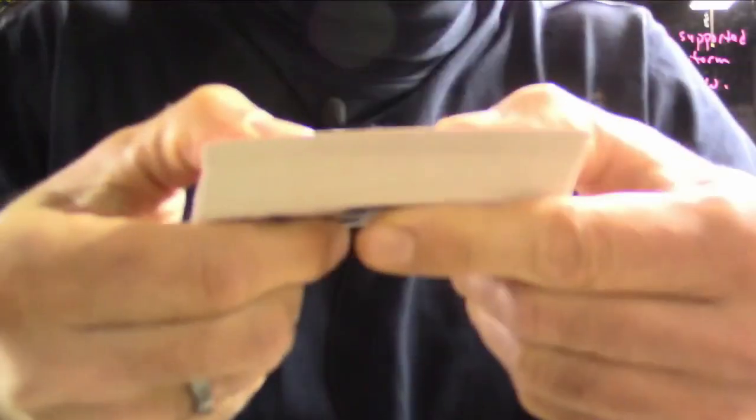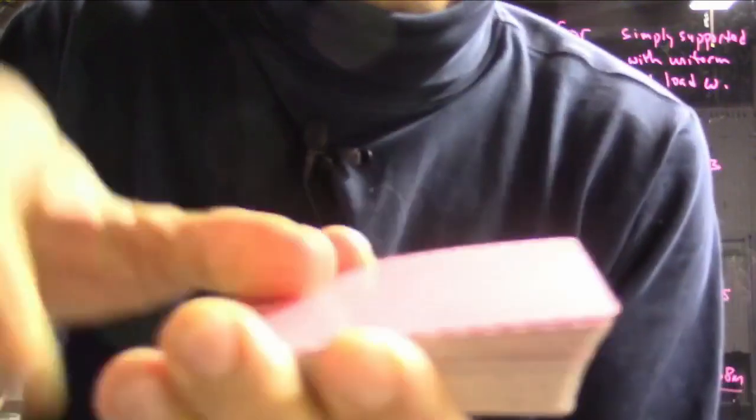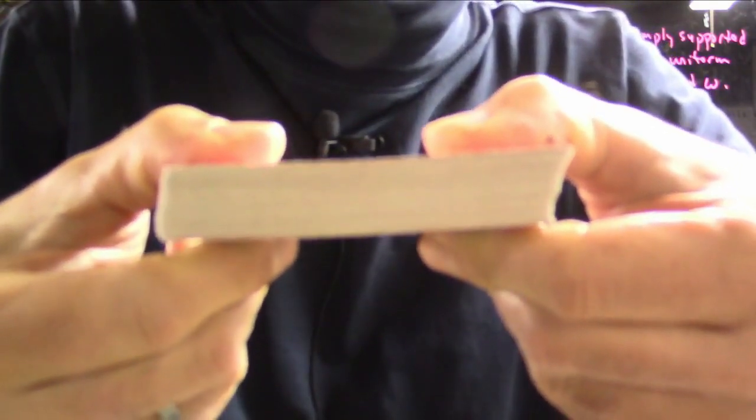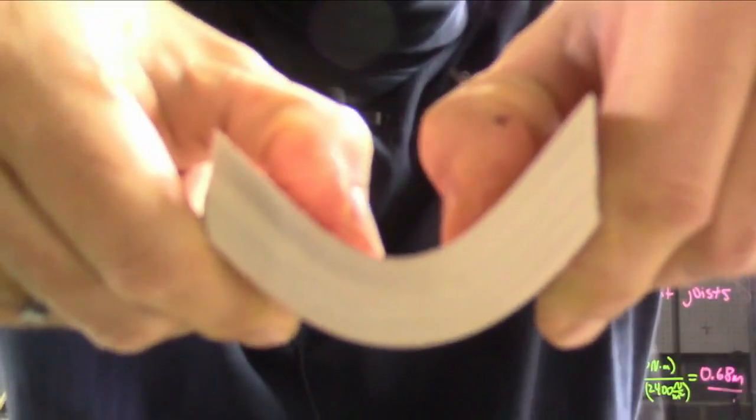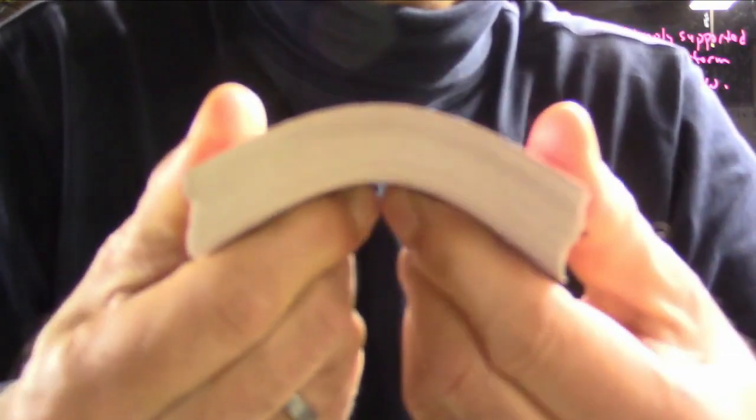If you try bending a deck of cards, you'll see that neighboring cards tend to try to slip past one another in this way. That is a shear phenomenon. If you imagine that all of the cards are initially glued together and then you bend the deck of cards like this, or like this, then since the cards on the top of the deck are bent to a different radius of curvature from the cards on the bottom of the deck, there will be this slipping past one another shearing phenomenon.